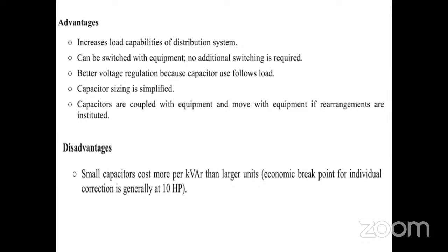Disadvantage: small capacitors cost more per kVAR than larger ones. If you are adding a capacitor at the tail end of the load, that means connecting one capacitor to each motor, and if we have 200 such motors, what will happen? The cost of 200 capacitors will be more.